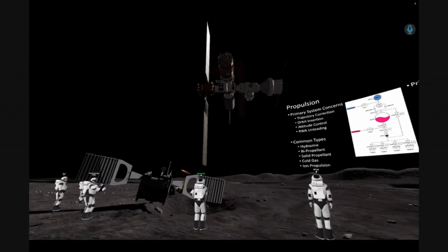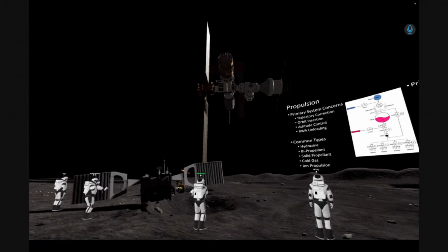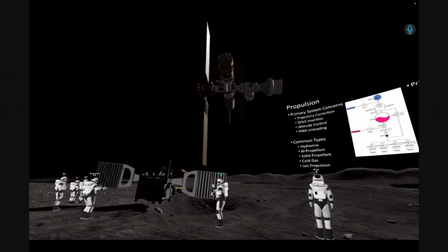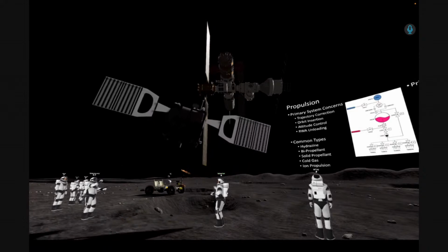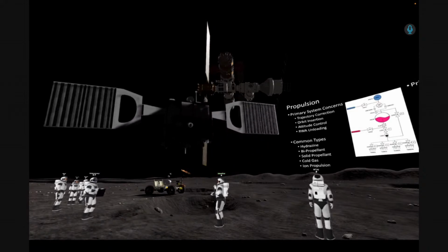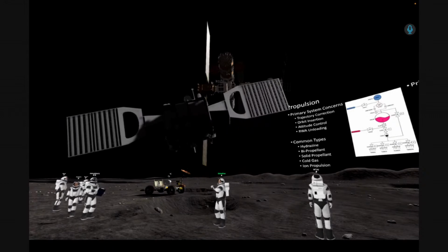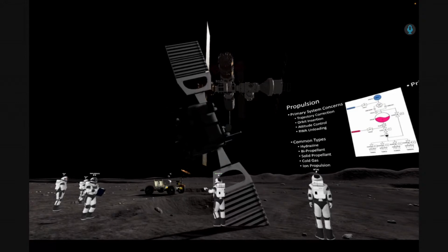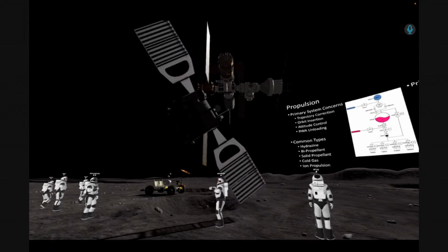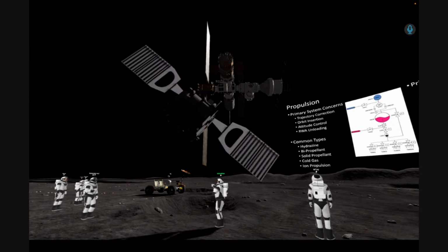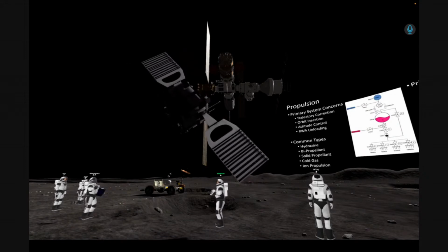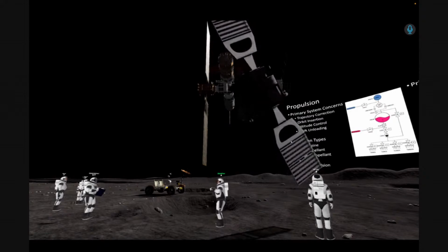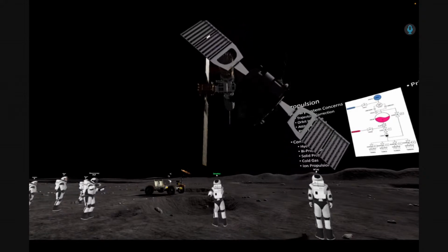That's the third point in the slides. So the first point of the slide is trajectory correction. This is what happens when you launch your satellite. You will have the satellite moving in a certain orbit, and this is something that we're going to study later on in orbital mechanics. So you will have your satellite move in a special way around the Earth, or around, I don't know, something else, the moon, for example, or Jupiter. And then you have to go, for example, from the Earth to the moon. So you have to insert your satellite into a different orbit than the one that it was having before. This is trajectory correction. So it's about the orbit itself.